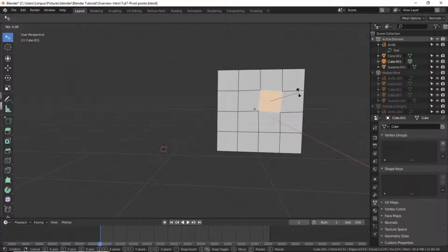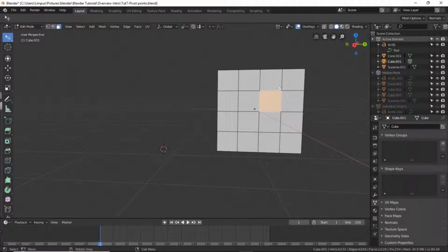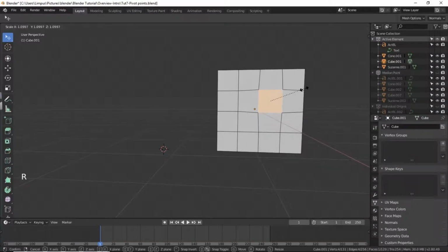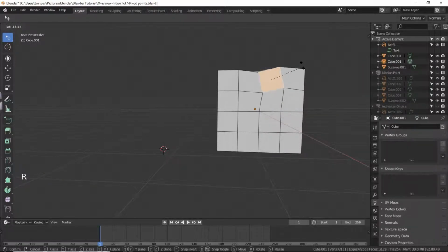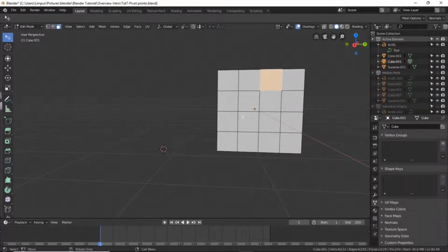If an unselected face shares one or more vertices with a selected face, then the unselected one will get some degree of transformation too. When one single face is selected, it becomes automatically active. You can see that when it is transformed, its vertices move, with the consequence that any adjacent faces which share one or more vertices with the active face are also transformed.